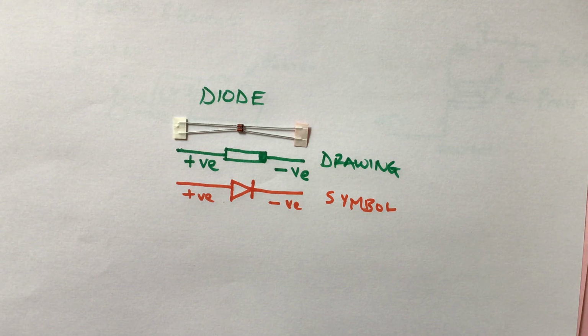Think of the motors and the places where you normally see a lot of coils or wire windings, places which can generate power. We normally use diodes in places where, when the circuit is put off, there is a small current still generated, and if it goes back to the circuit, it will end up blowing up things or bringing abnormalities to our circuit.